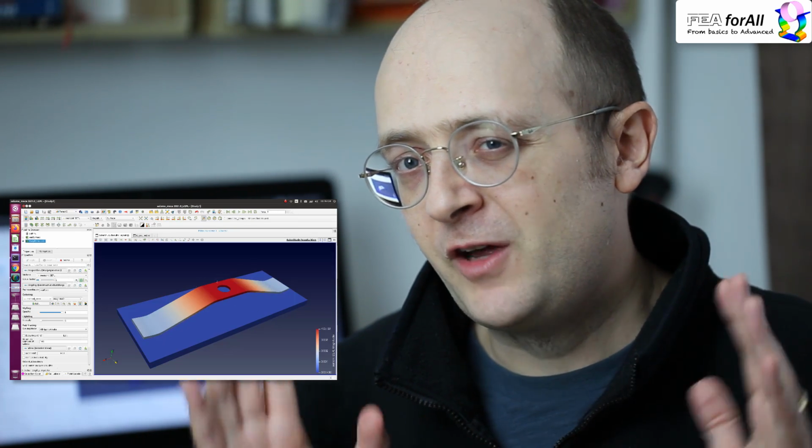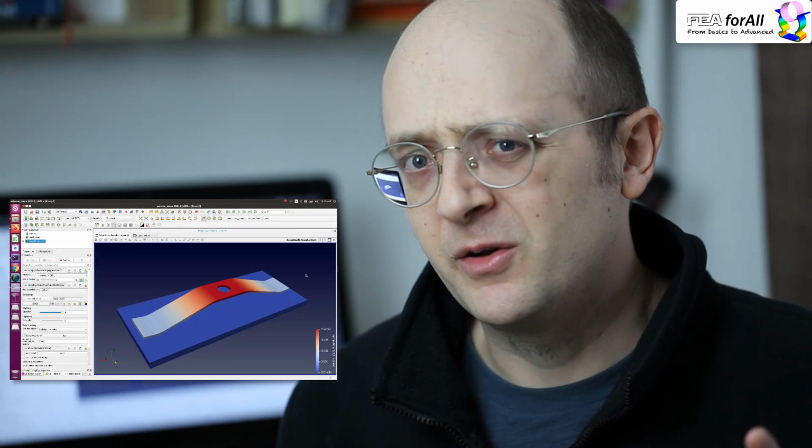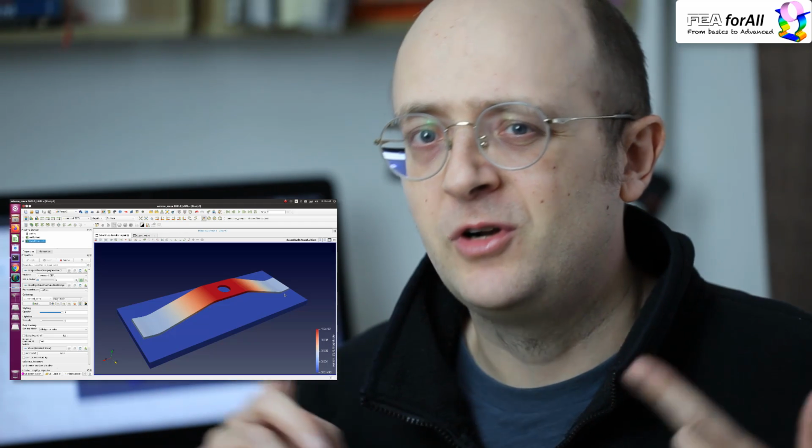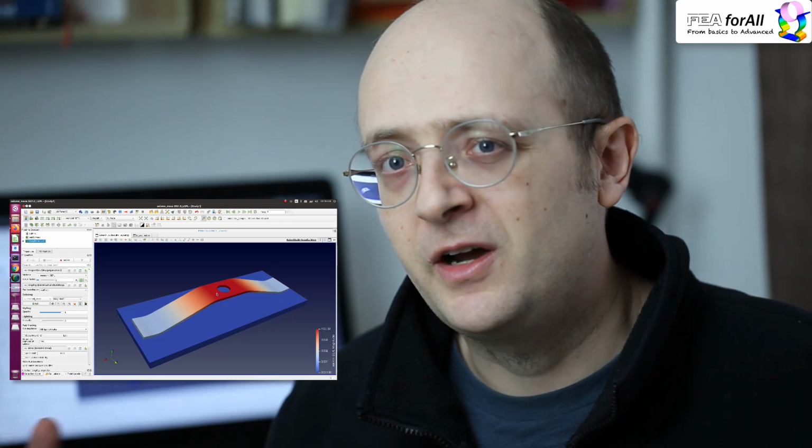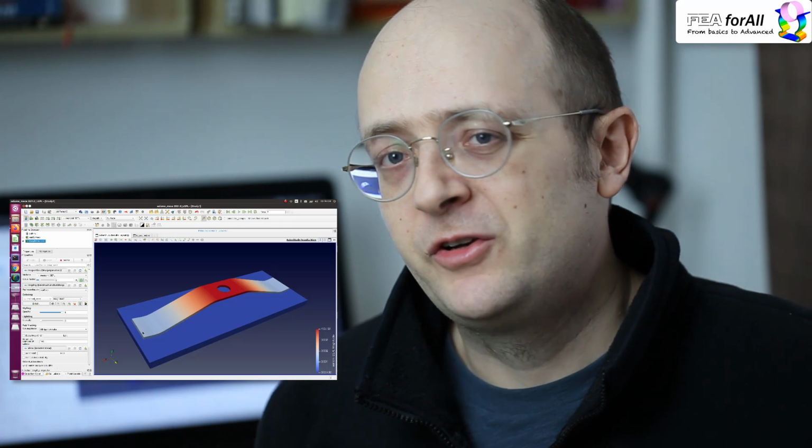I have avoided making this kind of simulation until now with Salome-Meca because it's very complex. You have a lot of things to think about. You need a very good mesh, you need to do a lot of tests, and you need to understand how everything works, especially nonlinear, elastoplastic, hardening curves, nonlinear contacts, different kinds of convergence methods. All of that is extremely hard.